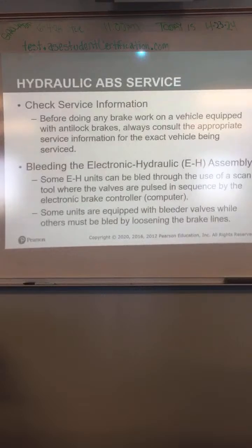On an ABS service, before doing any brake work on a vehicle with ABS, make sure you know what you're doing. Make sure you consult the service information. Bleeding electronic hydraulic assembly. Some EH units can be bled through the use of a scan tool, where the valves are pulsed and sequenced by the brake controller. You can use an automated bleed with a scan tool on some cars, and like I said, it will just pulse those valves in sequence.